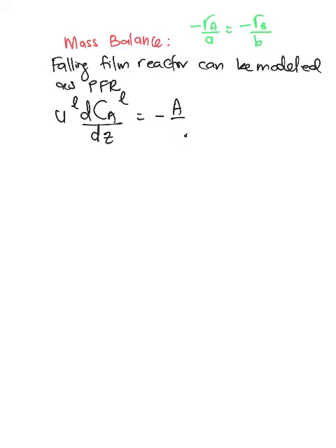Okay. So you can write it as A over V, Km, mass transfer, Km, C, concentration of oxygen in bulk fluid in the liquid phase, minus the concentration of oxygen at the external surface of the catalyst, and then we divide it by 2.